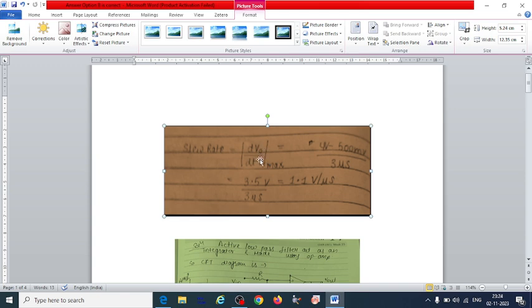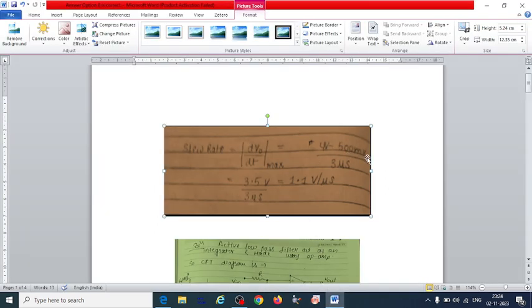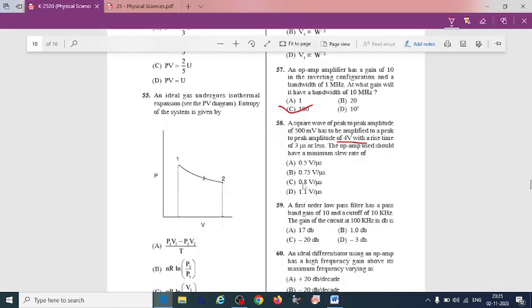voltage. So d output voltage divided by dt max, that is given by 4 volt, as we have here 4 volt peak amplitude minus 500 millivolt divided by the derivative with respect to time, that is 3 microsecond. 3.5 divided by 3 microsecond we will have, then this ratio is equal to 1.1 volt per microsecond. So the correct answer is option D.